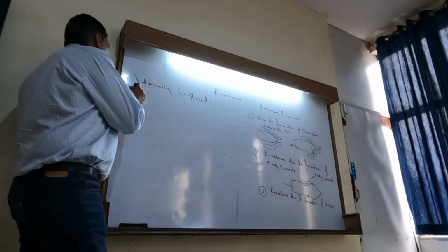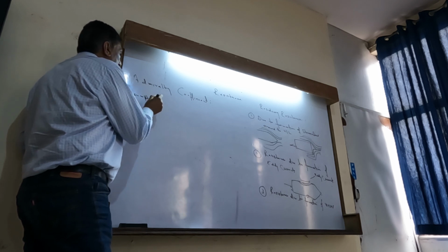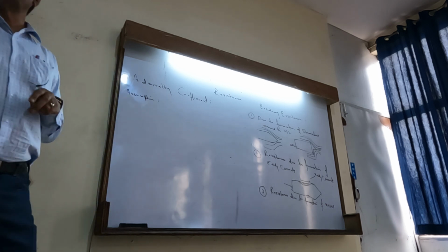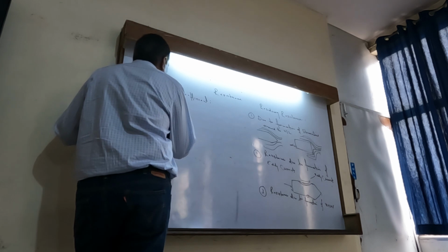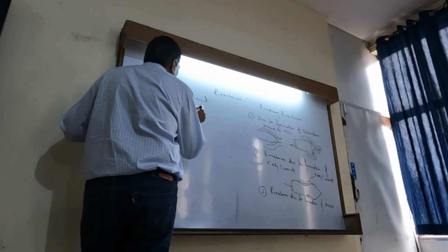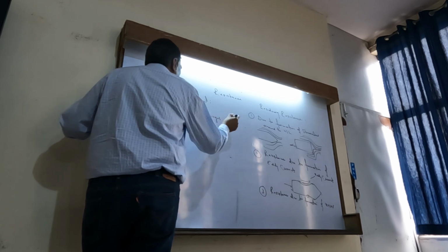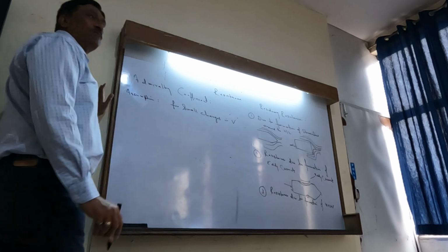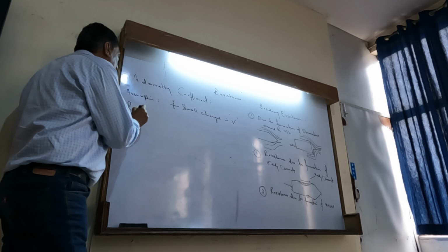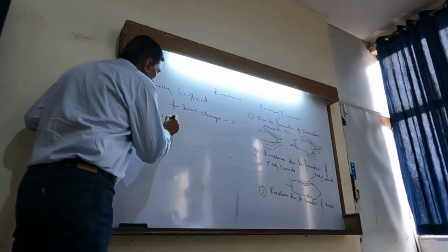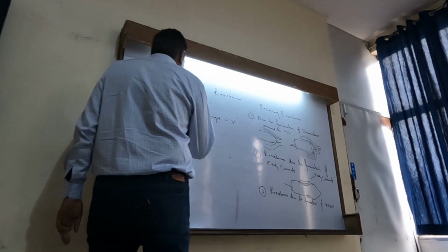So here they have made an assumption for small changes in V. What is V? Speed of the vessel. We can say total resistance of the vessel is proportional to rho S V raised to power n. And who said this?